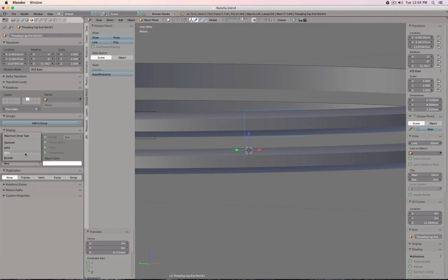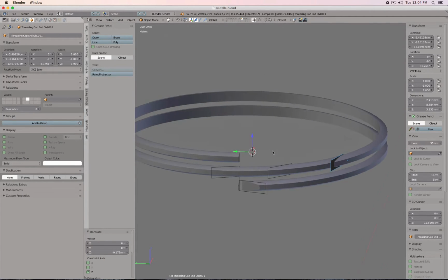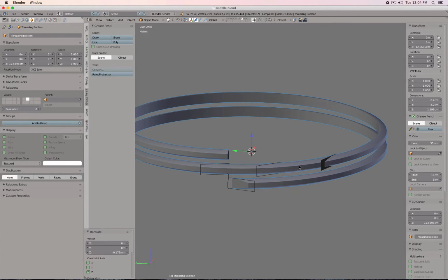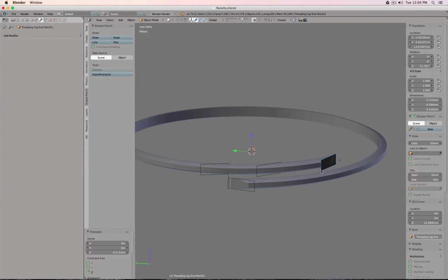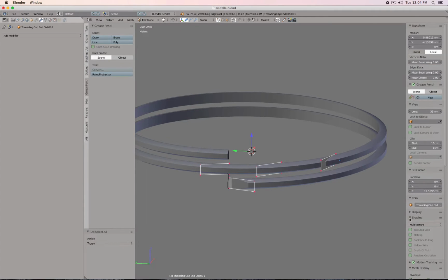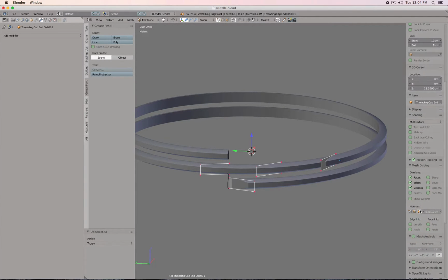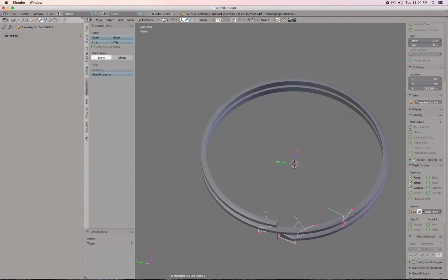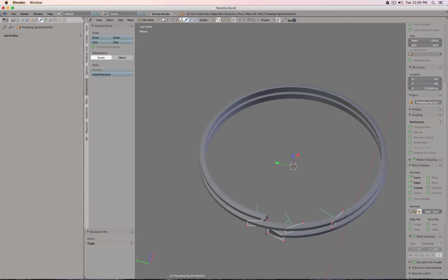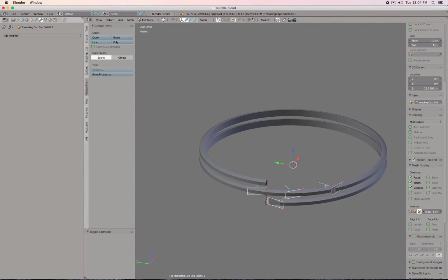This object is set to wire, so in Solid you see it's just a face. And then I add this to Boolean, and there it's cut. Also, the orientation of each face is important. So you see wherever the face looks to, everything up to that face will remain, and then everything afterwards will be discarded. So for example, if I flip this,